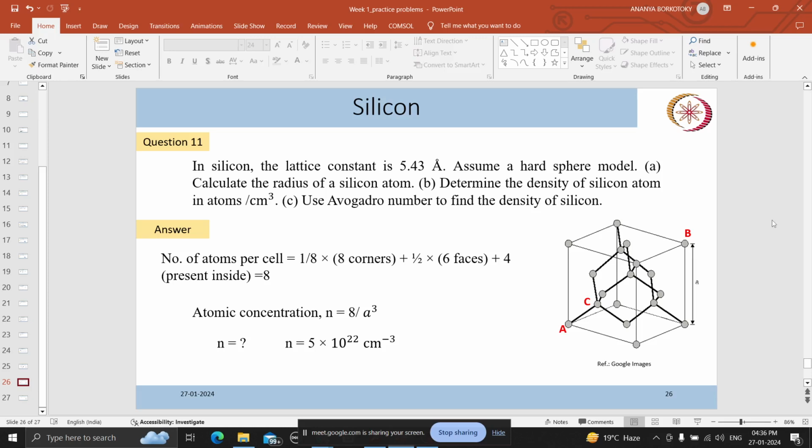See, that way it will not be called doping. Ultimately the atoms will go to the lattice sites. If the atoms are not in the lattice sites, those will be called defects, right? We want dopants, not defects. If those are in lattice sites, they will contribute to the covalent bond, like there will be one missing electron or an extra electron.